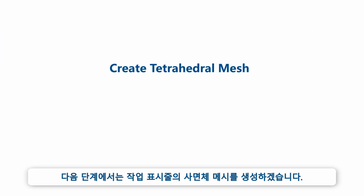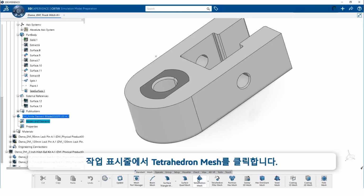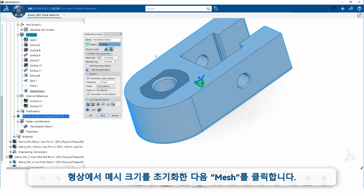Next, we will create a tetrahedral mesh. From the action bar, we click on Tetrahedron Mesh. We select the part body from the tree as the support. We verify that quadratic elements are selected, then initialize the mesh size from the geometry and click Mesh.